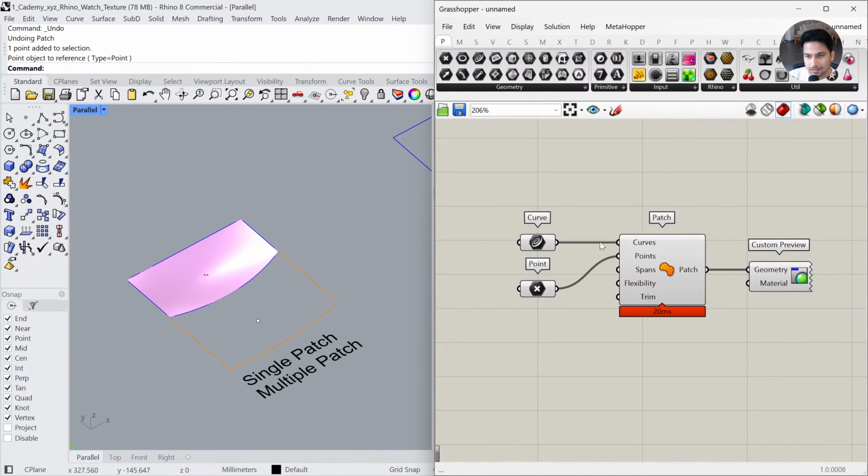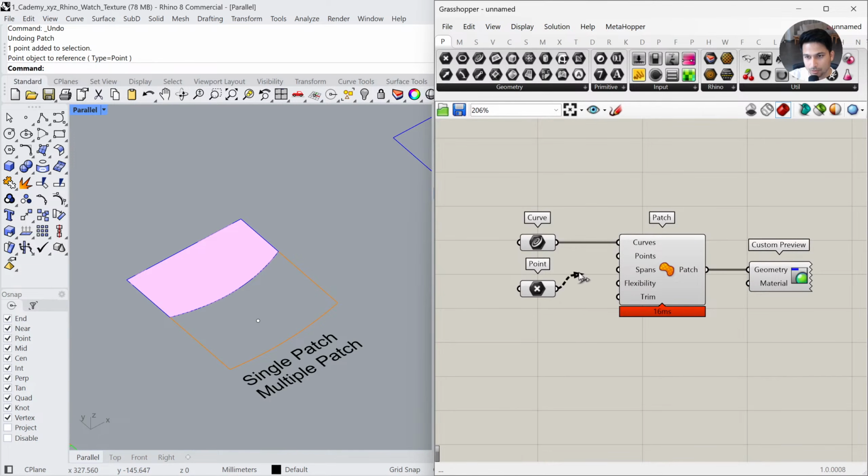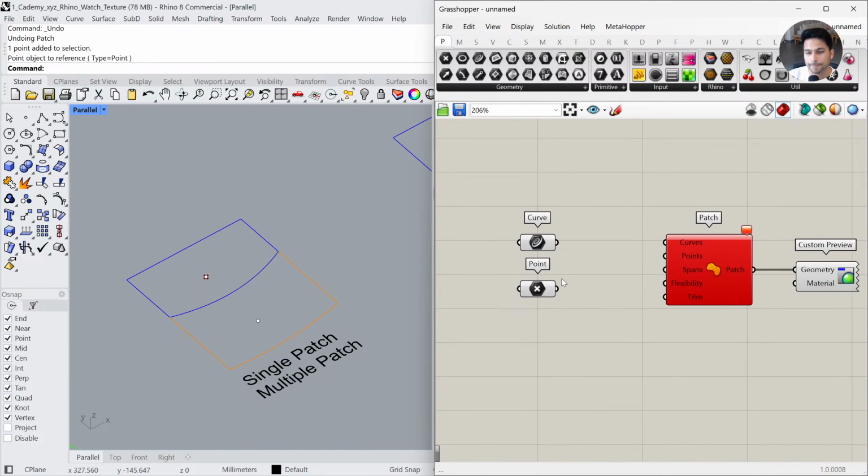In order to disconnect the cables, you can press and hold Control, and then when you make the cable, it disconnects it. Normally connecting connects it, but while pressing Control, it disconnects it. You can also see there is a red arrow next to the cursor when you press and hold Control. Okay, so let me disconnect these two cables.